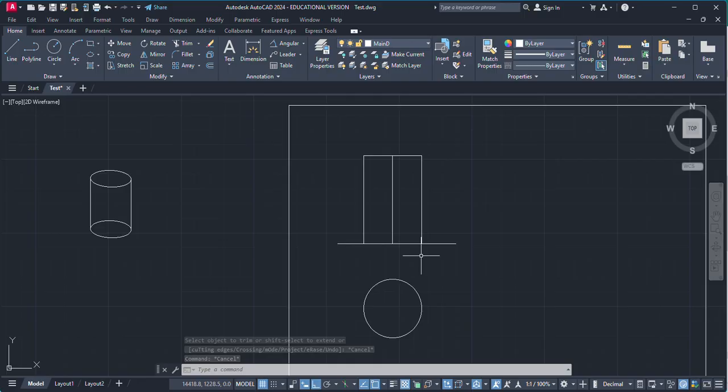This is what we have done in orthographic projection. Similarly, we have done multiple things. With this front and top view, we have tilted our body such that the central axis of this cylinder makes an angle with HP. Suppose it is making 40 degrees with HP or 40 degrees with VP. So the main thing in orthographic projection is the front view and top view. We have projected our 3D object in a 2D plane with the help of two dimensions.